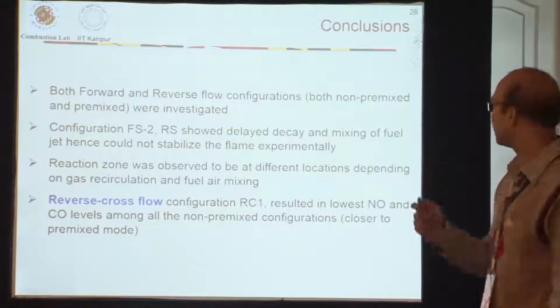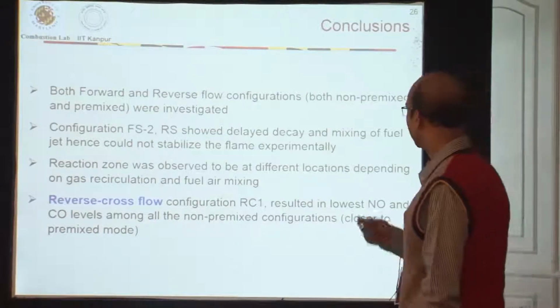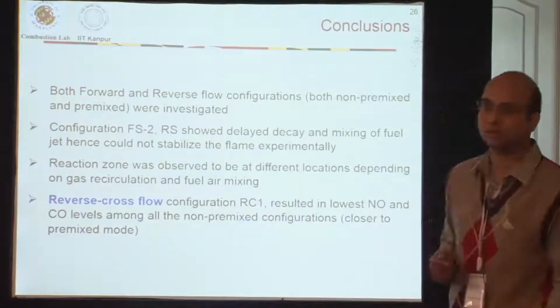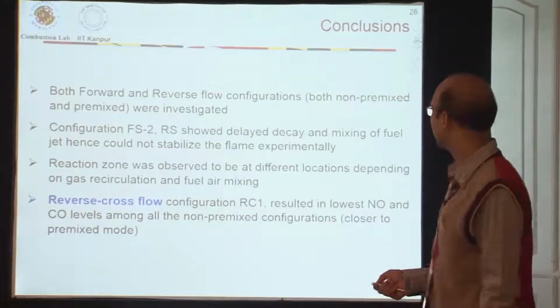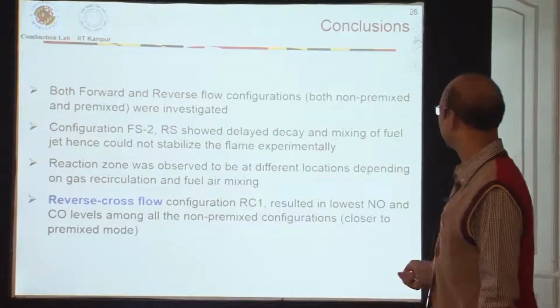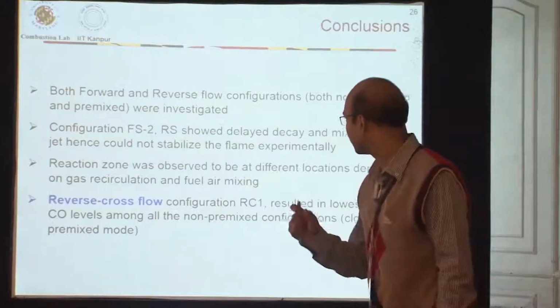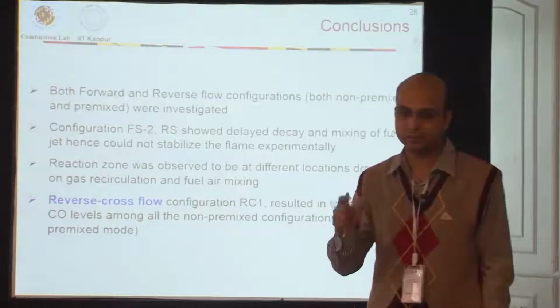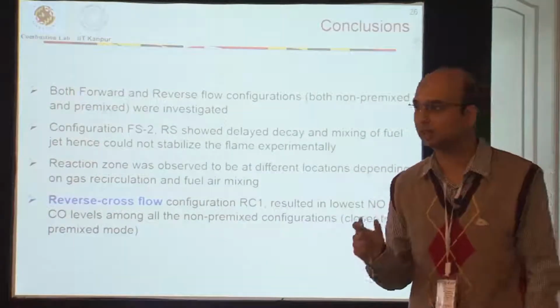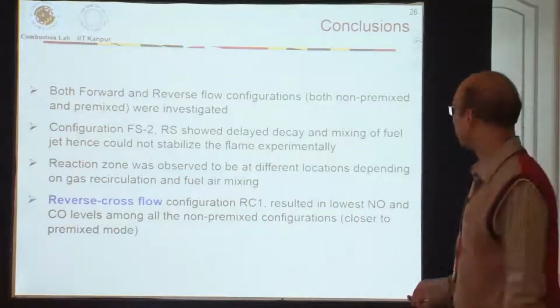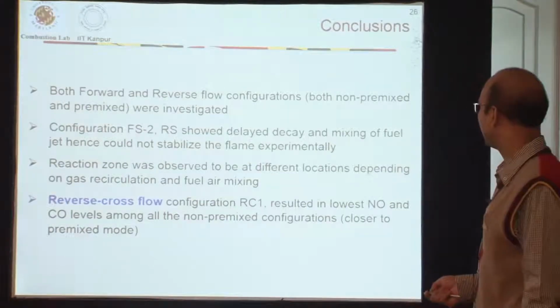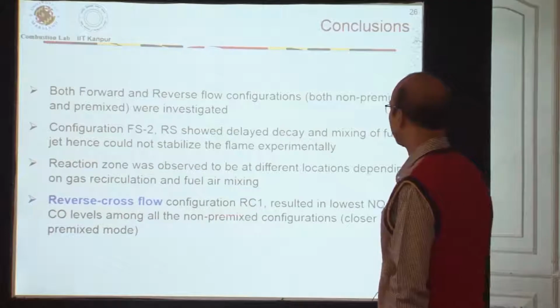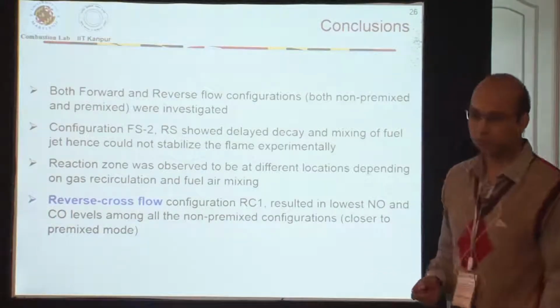You have to smartly design your combustion chamber and smartly design the gas recirculation inside the combustion chamber to get a stable flame. And for both forward and reverse flow configurations, your reaction zone is situated at different locations, and this depends on your flow field as well as fuel air mixing inside the combustion chamber. And in the end, we found that the reverse cross flow configuration was most desirable.